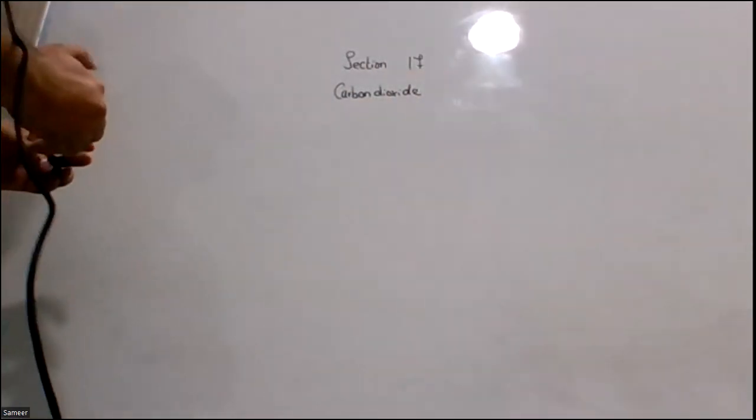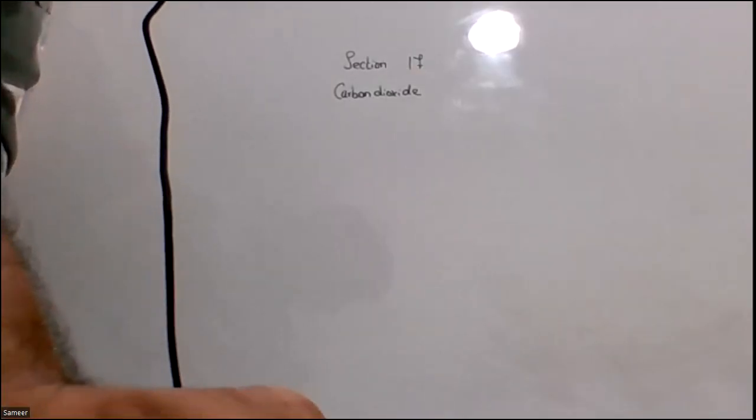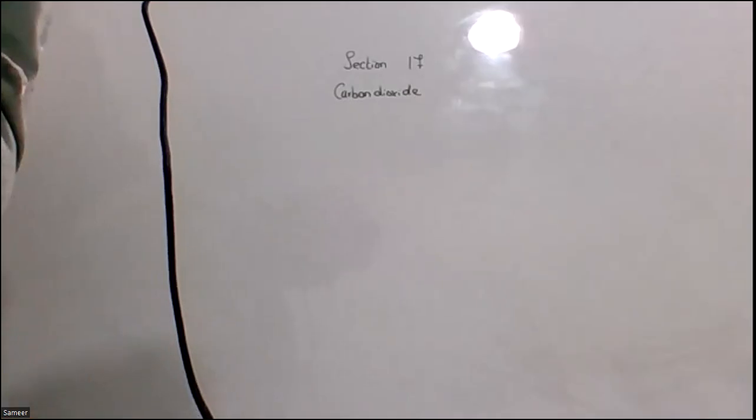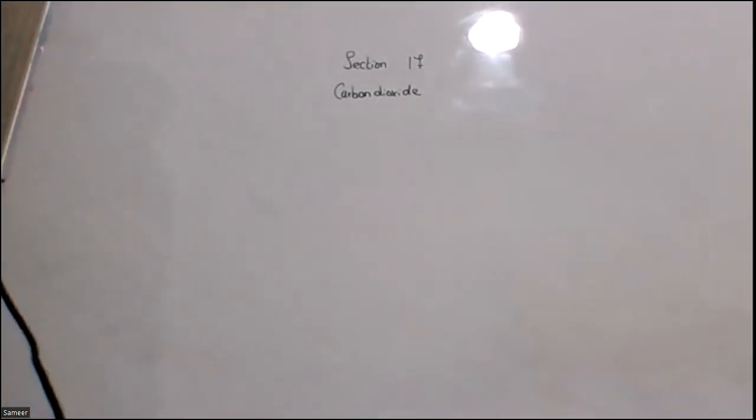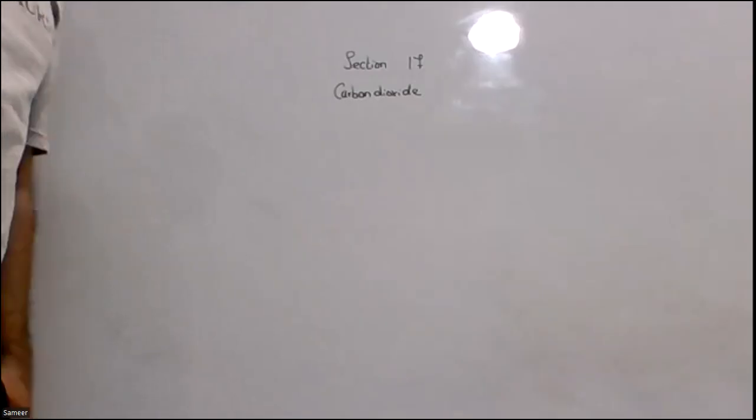Starting our discussion from carbon dioxide systems. Carbon dioxide systems are the most widely used type of system that we have been using. And why we tend to use them is because there are some very good properties of carbon dioxide. First of all, a limited amount of carbon dioxide is not dangerous for human beings. Regardless of that, if I use it as a total flooding system, meaning complete occupancy, it removes the oxygen very effectively.